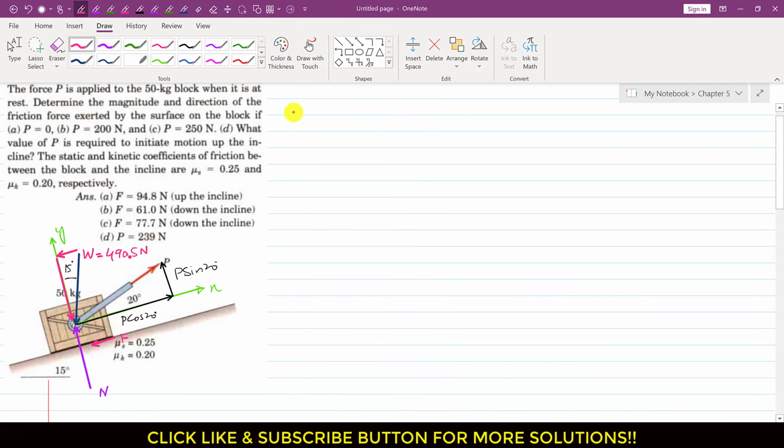Now let me assume that the system is in equilibrium. So for equilibrium, we will apply the summation of forces along x equals 0. If we apply the summation of forces along x, we can see that we have this P cos 20 force acting in the positive x direction. So I will write P cos 20 degrees. And similarly, this F force is acting in the negative x direction, so I will write minus F.